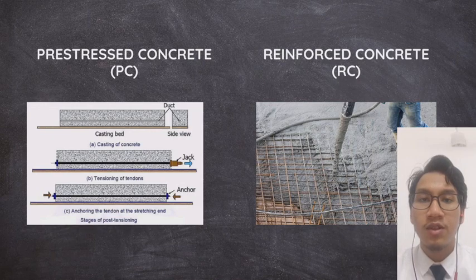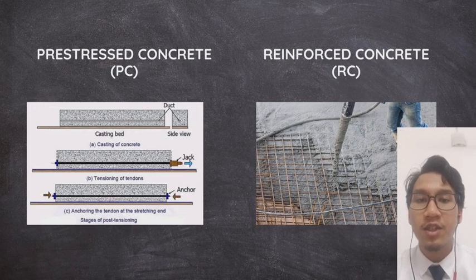While reinforced concrete is a concrete in which steel is embedded in such a manner that the two materials act together in resisting forces. The reinforcing steel rods, bars, or mesh absorb the tensile, shear, and sometimes the compressive stresses in the concrete structure.